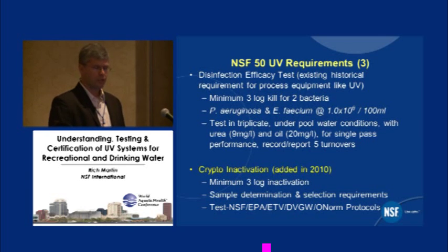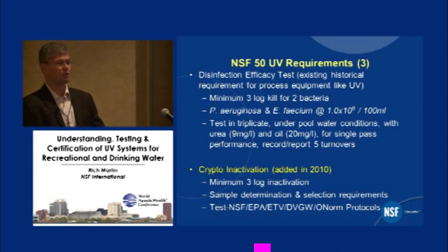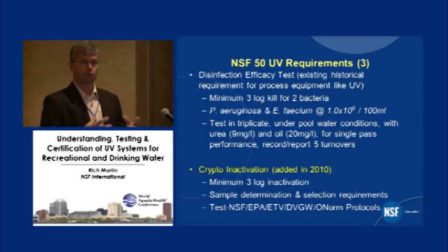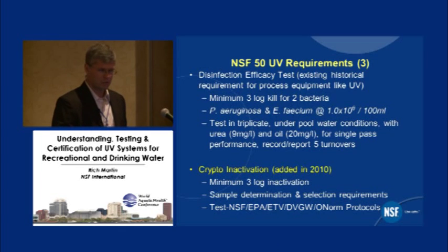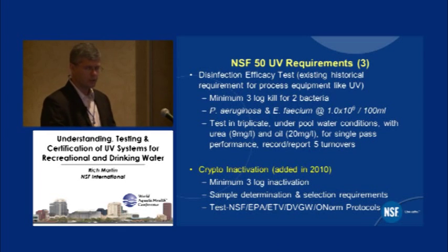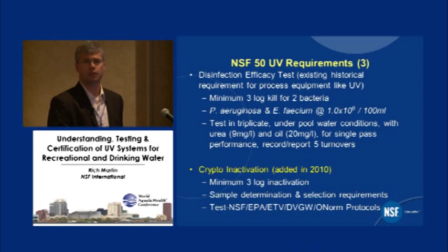So it's really just to make sure you can get at least a 3-log kill after this type of dosing. But it's not just dosing the organism, it's also dosing contaminants that are more representative of a really grim kind of pool operating condition. So again, with oil and urea content also dosed into the water, it makes it a very challenging test. And then beyond that, in the 2010 edition, that's where the cryptosporidium requirements were added.